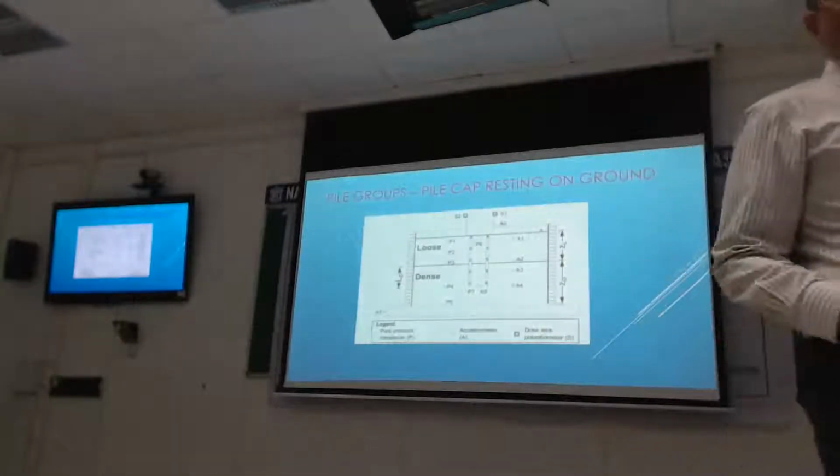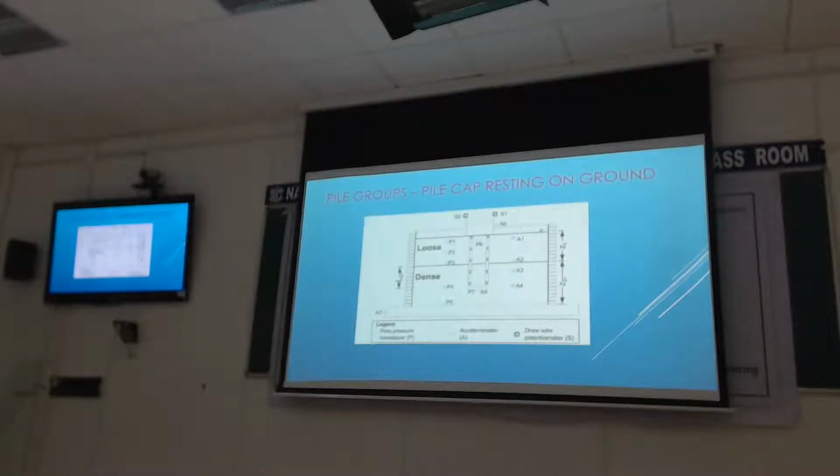So the next set of tests we did were with the pile cap in contact with the surface, which is more like the field case. When we say they are in contact, they're always a little bit embedded. We push them until they come into contact. As you G up, they will undergo some settlement. So they're always embedded by a few millimeters, a few millimeters times G level. So it's like a quarter of a meter or half a meter embedment into the ground. So we said, right, let's try these.